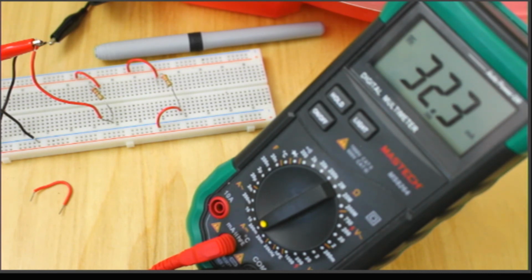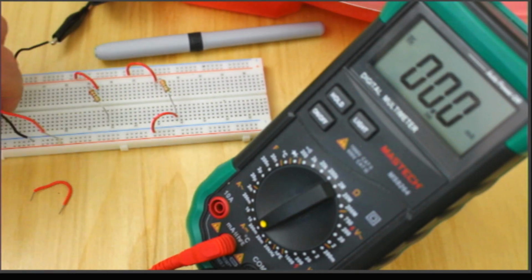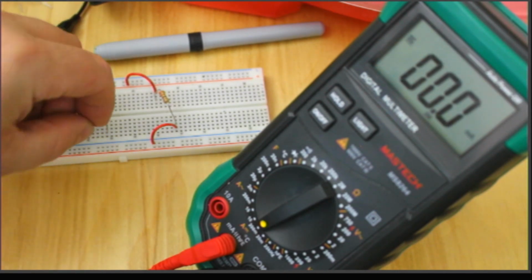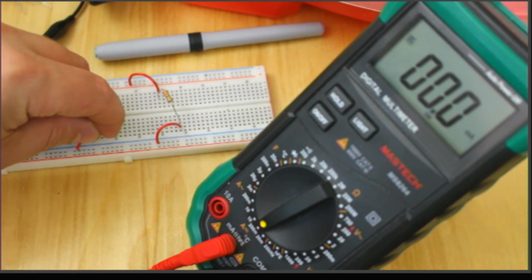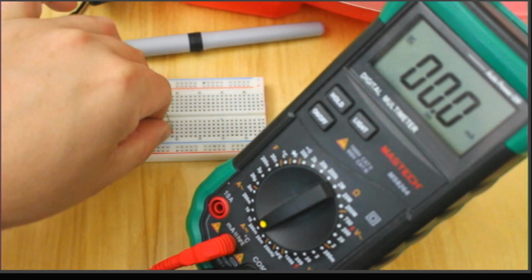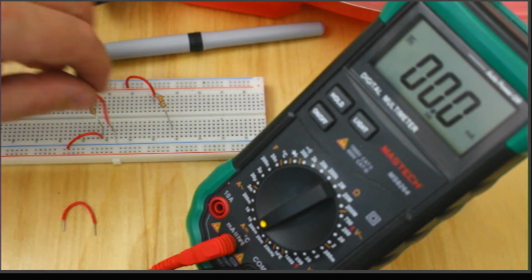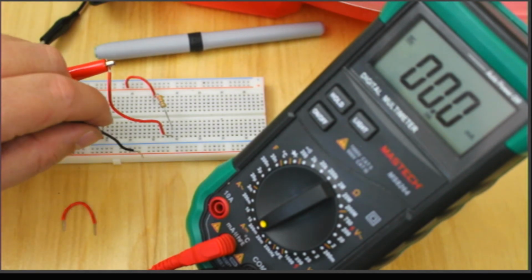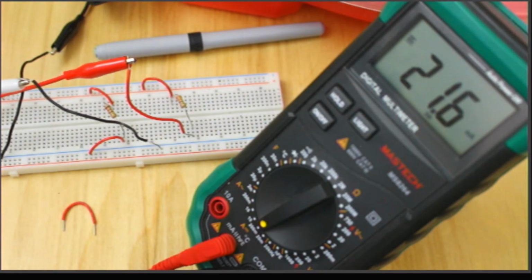Okay. So if I want to measure the other branch, I can take my meter out. So if you ever get this, like on the exam, or if you get it on your labs or whatever, make sure you measure what your voltage is every time out of your battery. Okay, so I'm going to do the same thing with this other branch. I'm just going to take that bottom wire out, and I'm going to put the positive lead of my DMM into the leg that touches the resistor, and I'm going to put my negative lead of my DMM into the bottom here. So there we go, 21.6 milliamps, and we expected 24.8.